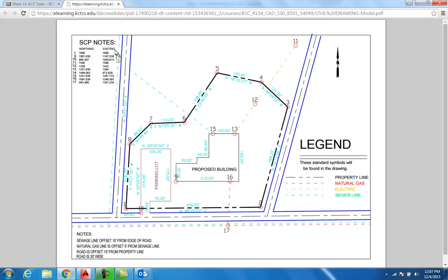And why they're saying northing and easting is because your origin is always going to be in the lower left corner, meaning everything is going to be positive. X is going to be positive, everything in Y is going to be positive. And again, X is what they call easting, because that number in easting is always going in the positive direction of X. Now northing is always going to be going above the origin, which puts everything in Y positive. So that's the reason you have northing and easting. That's the reason you don't have southing and westing. It's all going to be positive, positive.